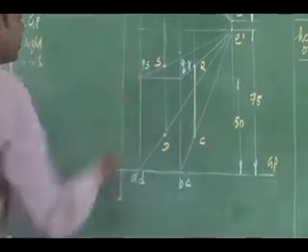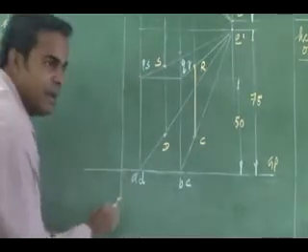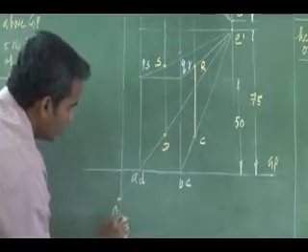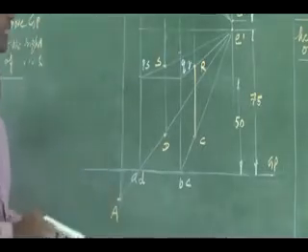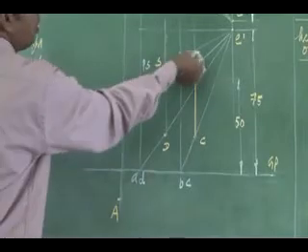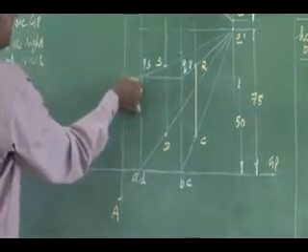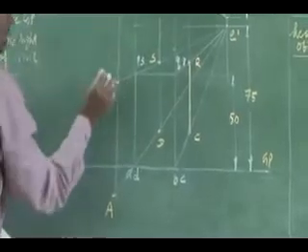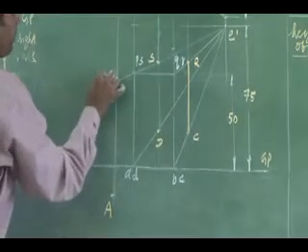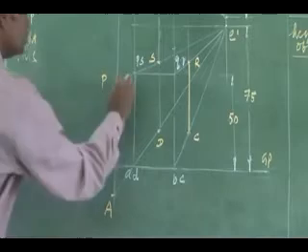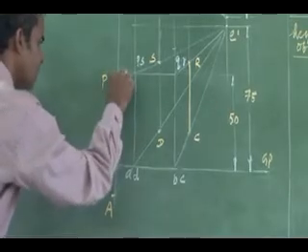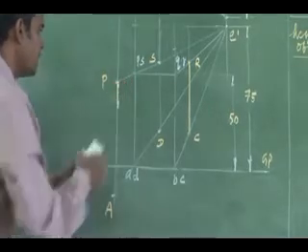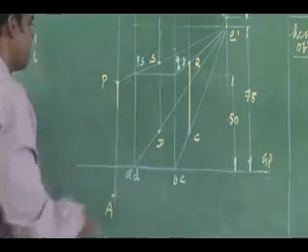That location is going to be my perspective location of A. Similarly, P: in the same manner I can extend it to where it intersects the AB projector, and that is going to be my P. So this is the enlarged edge AB in my perspective.